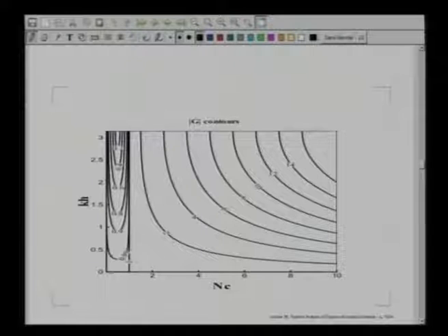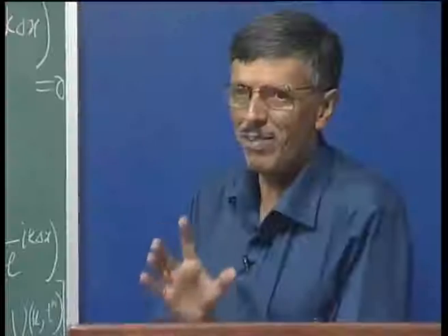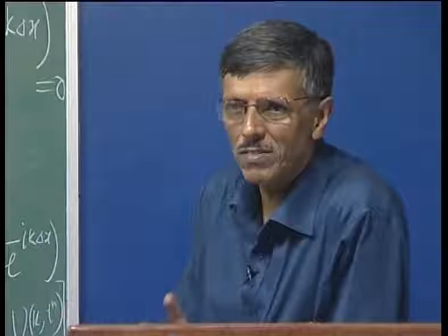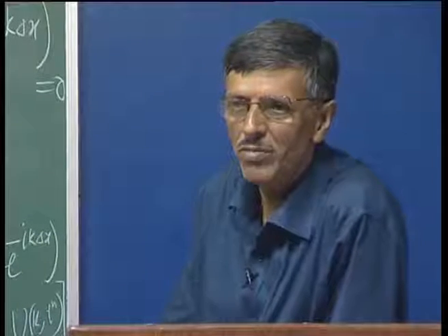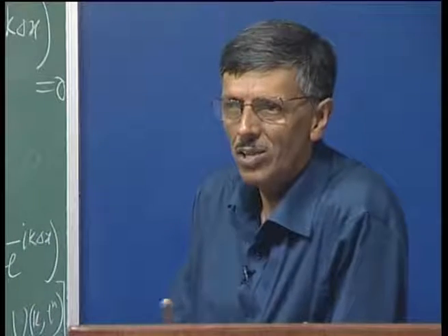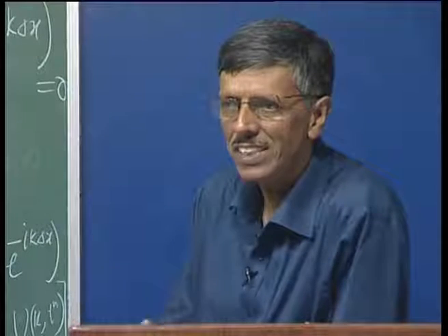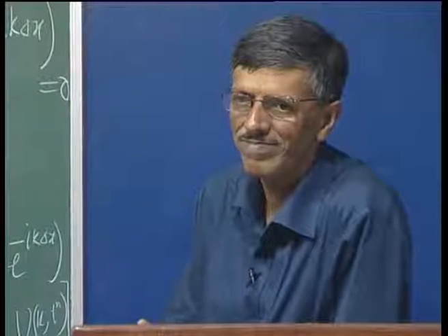Whereas, if you take n c exactly equal to 1, what you are getting? G is equal to 1 everywhere, and that is your exact solution. So what we have learned is that upwinding by itself is not bad, provided you do it physically, and here doing it physically is equivalent to taking n c equal to 1. So you understand that there is nothing wrong with upwinding per se, but if you overdo it, say instead of taking n c, it means what?